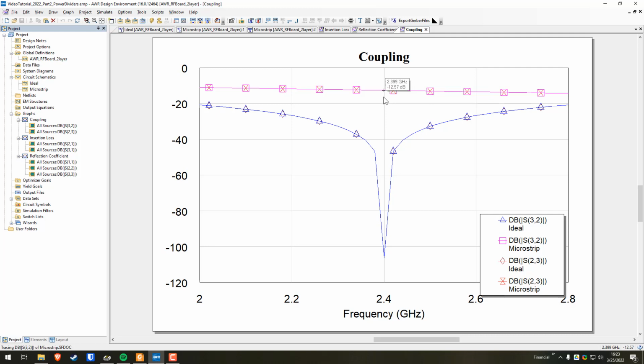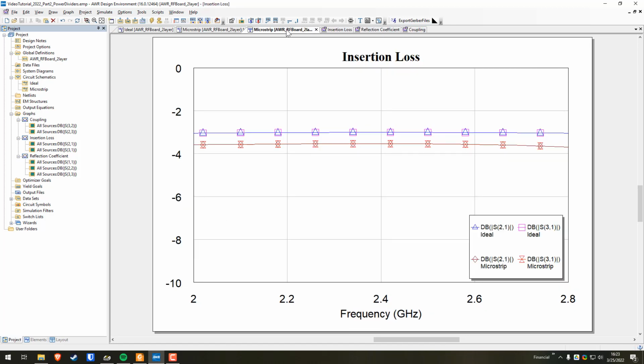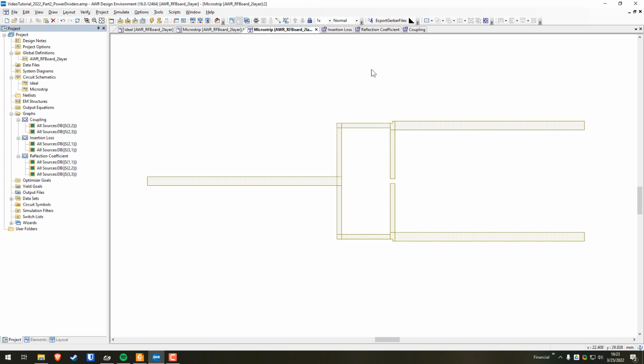It's quite a bit, right? So what that represents is basically like 1/100th in linear. So, sorry, 1/10. That's 1/10, and then it's almost 3 dB, so it's actually 1/20th of connection between the ports. And we can improve that by doing some tuning, which, matter of fact, let's do a little bit of tuning.